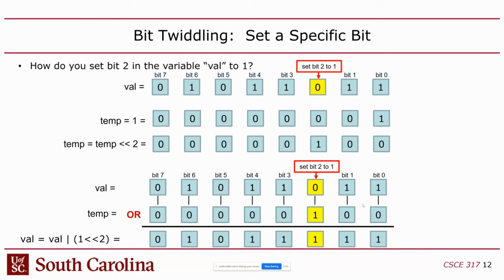Now, you might say, well, you're using magic numbers in there, which is true, and obviously you can replace those with constants, which we'll do here in a bit. I'll show you how to do that. But basically, this is kind of what it would look like after the preprocessor gets done with it. So you have 1, you shift it 2 bits, you merge it in.